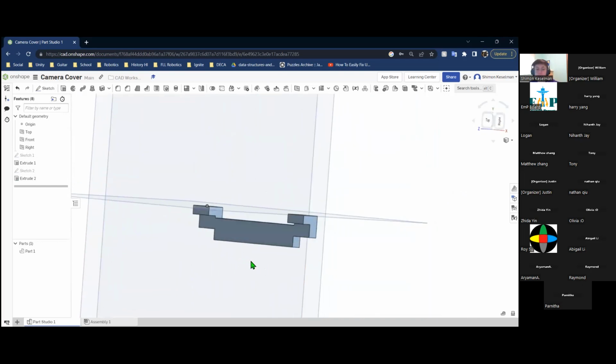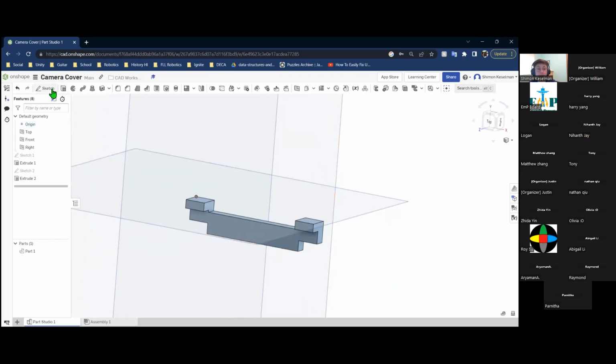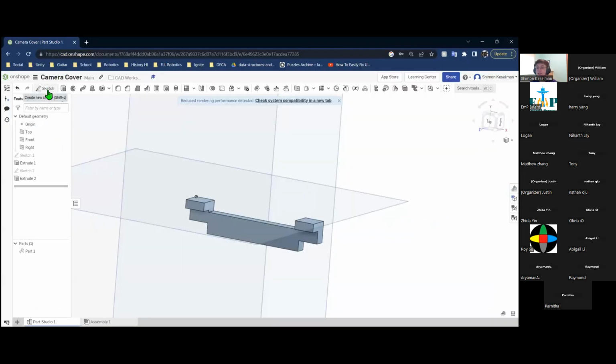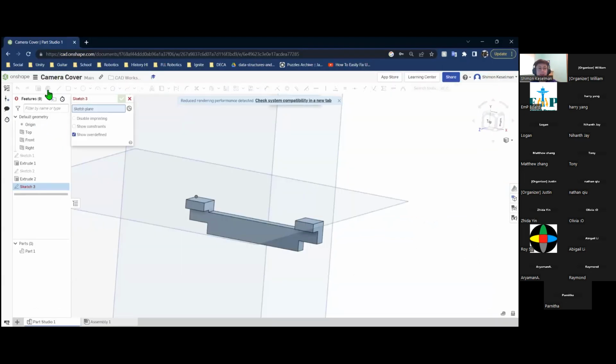Awesome. So now that we have this, what I'll do is create the back side. The back side here looks like it's the same as the front, but just to simplify the design, I'll just make a big rectangle in the back. So going back to Onshape, to do that, again, in the top left, click Sketch, click on one of these faces to make the sketch on that plane and then align ourselves with that plane on the cube up here.